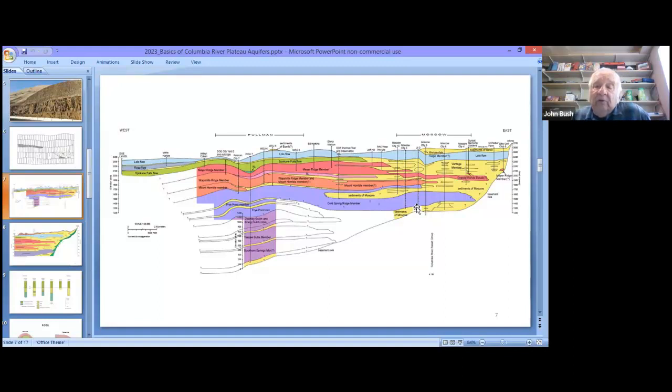One of the reasons we don't always have good numbers is that rarely are pump tests run on the sediments. To put a screen in the sediments along through the well is very expensive, very difficult. When you drill the sediments, they come up as a mishmash of coarse grain and fine grains. You don't know exactly where the sands are. So it's pretty practical for an engineer and the driller to case off those sediments and get the water out of the basalts because they're more stable.